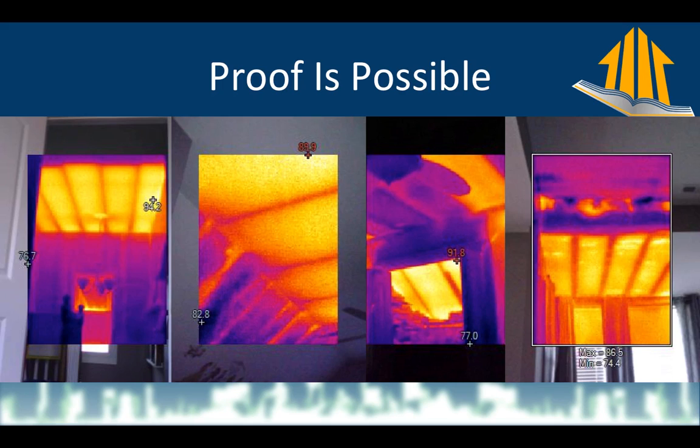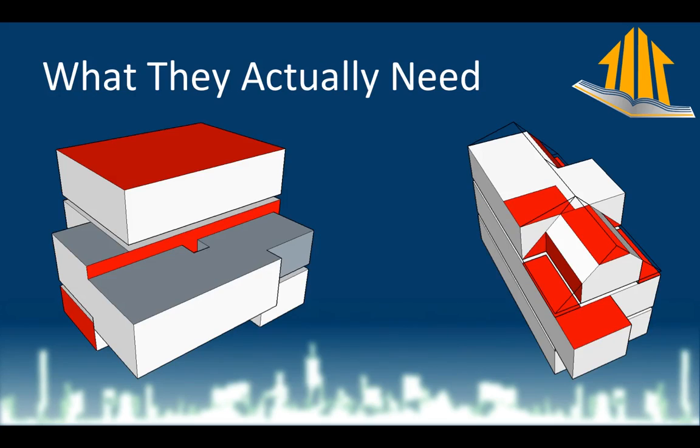You could do this exact same analysis on a 70-degree day, and it would be fine, because remember, the roof is black. So these people do not need new windows. What they actually need is to be able to define the enclosure much better. So we need insulation and air sealing to be in the right place and to be in the right amounts. And that's all. And that's a lot less than $30,000 of new windows. So great news for my clients. They were delighted.